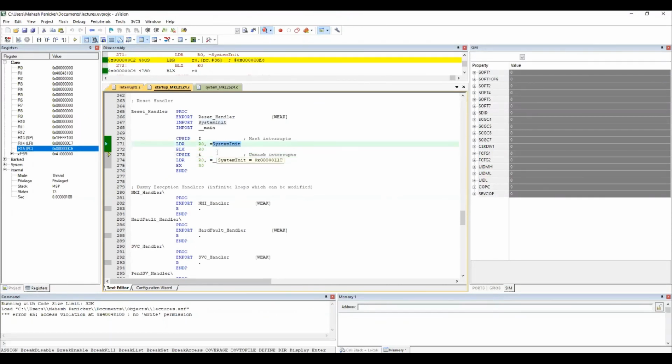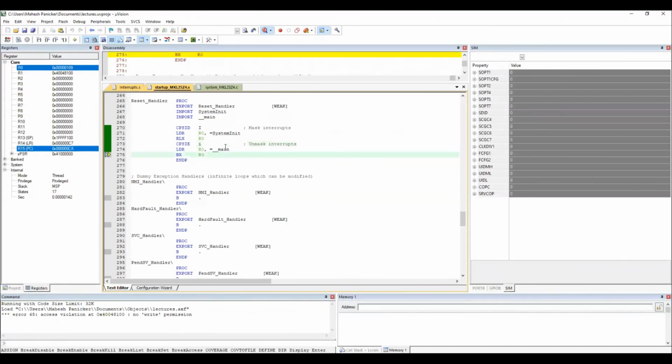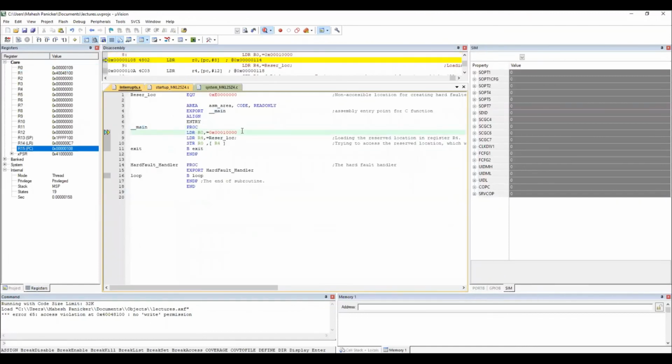So far you are blind. Previously, when you were running this code in lab, you were blind to it. Now you really know what is happening. So this enables the clock. And now you enable or unmask the interrupts. So it disables all the interrupts, sets the clock, and enables all the interrupts again. Typically all interrupts are disabled, but some system interrupts by default are enabled. You are enabling it back. Now here again, you are loading the address of the main and branching to main.